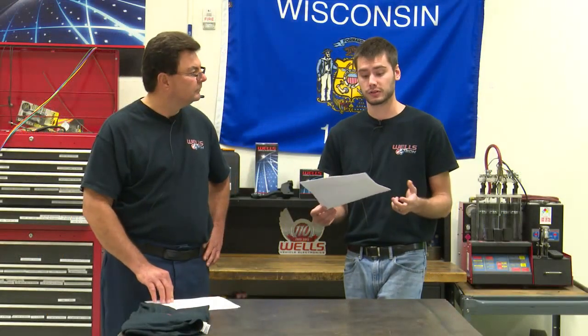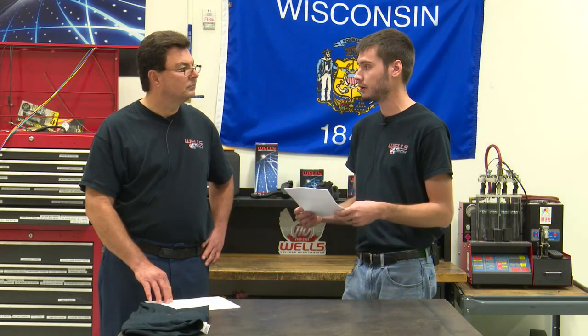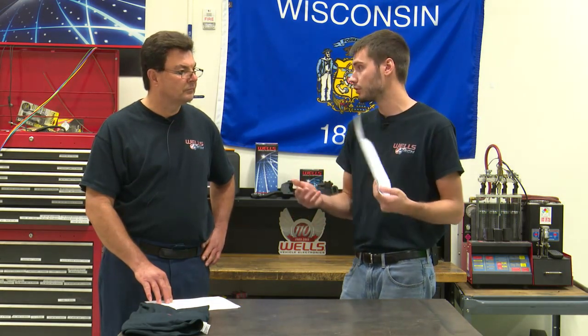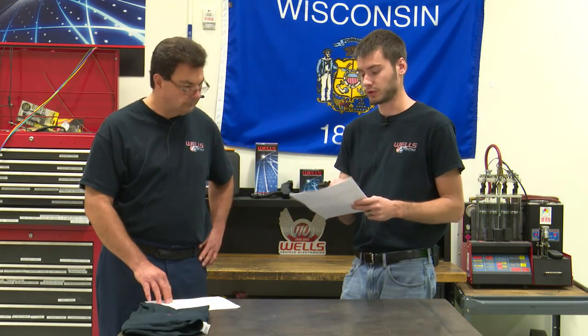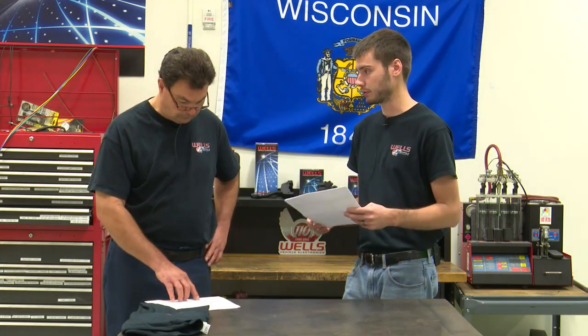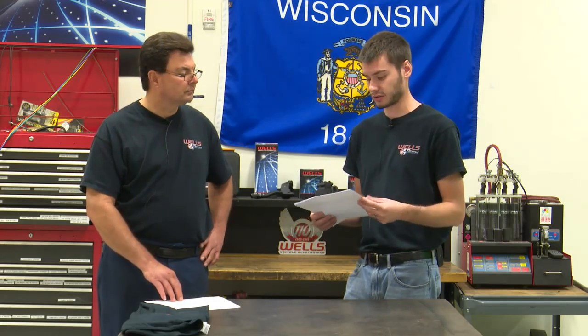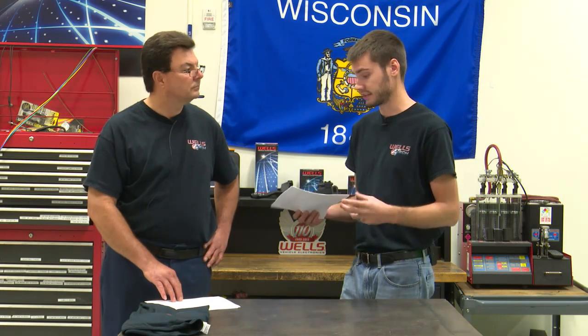That is really important to know. So you have a vehicle coming in, customer complaint, vehicle goes into reduced power mode. Say you have a bunch of codes in there. You pull this 121, you can see that that is what's causing the reduced engine power mode. That's how you can know what exactly the computer is going to do or command when it sets a specific check engine light, or a specific DTC.